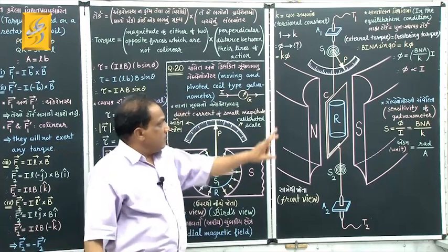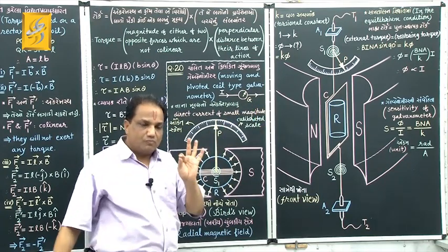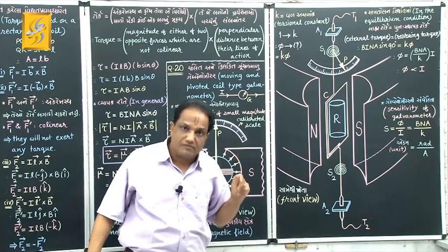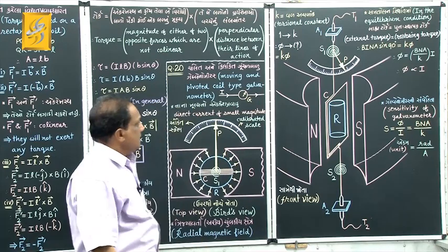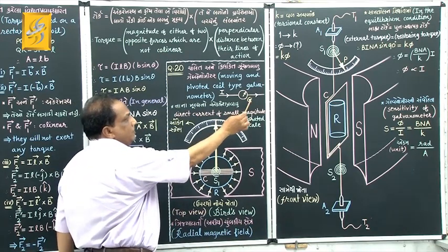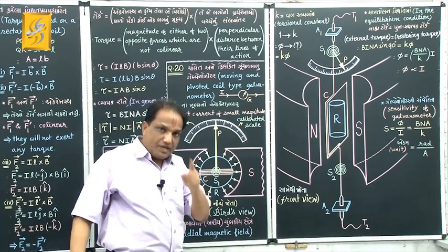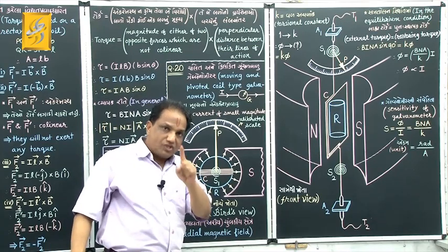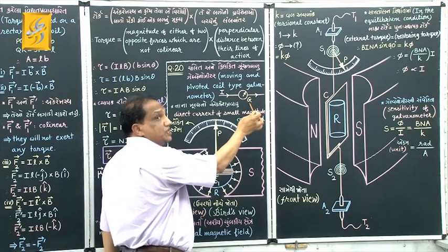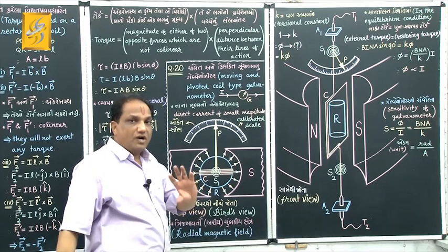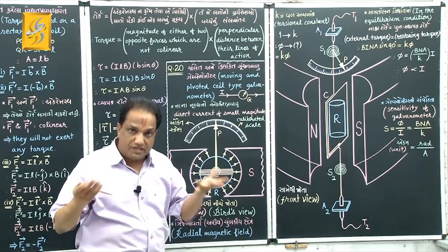So basically a galvanometer is used in the circuit to check the presence of a small value of current passing in the wire, okay, passing in the circuit. Got it? Fine. Now, in the construction of the galvanometer, we will see just now some copper coil is used. It has some resistance which is called internal resistance of the galvanometer, shown by symbol capital G. It is of the order of 100 ohms. Around 100 ohms, the practical galvanometers have their resistances.